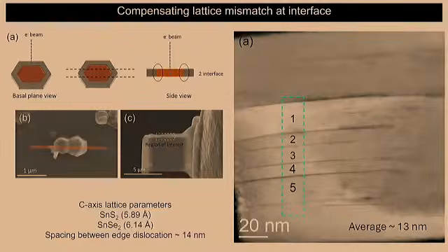So the interesting thing here is that we have tin sulfide here, on this side tin selenide. We are seeing some sort of cracks that are forming in the tin selenide. The lattice parameter of tin sulfide is 5.89, which means that it's closer, and tin selenide is larger, which means that this region is under tensile stress. Okay, and this of course shows you there are cracks.